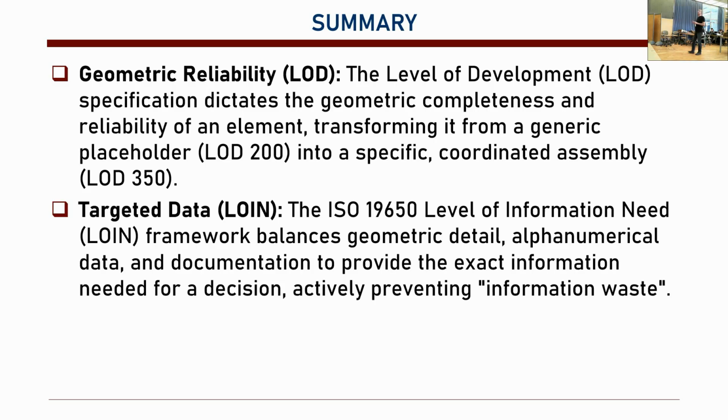We have geometric reliability, LOD. LOD is still used because we define the development of, we define different stages in LOIN with LODs. We have tables, and there we describe what LOD we want. But this is overall LOIN. Okay? LOD is a way of expressing LOIN, we can say, in terms of geometry and information content.